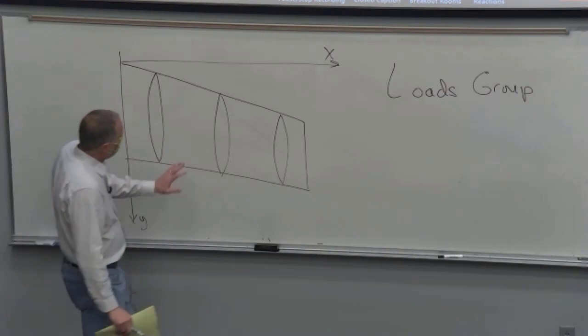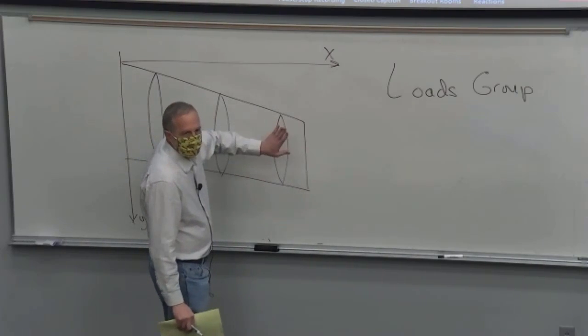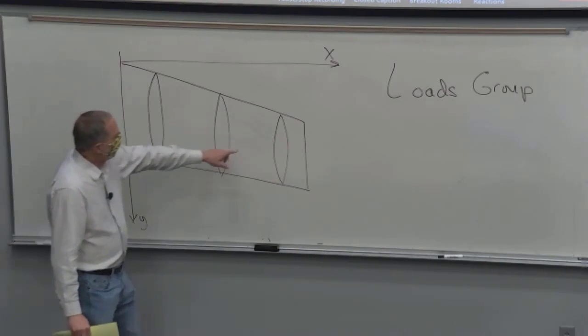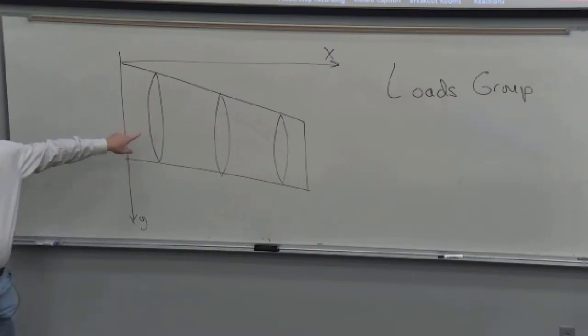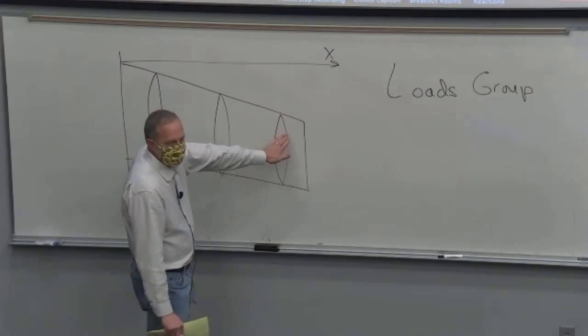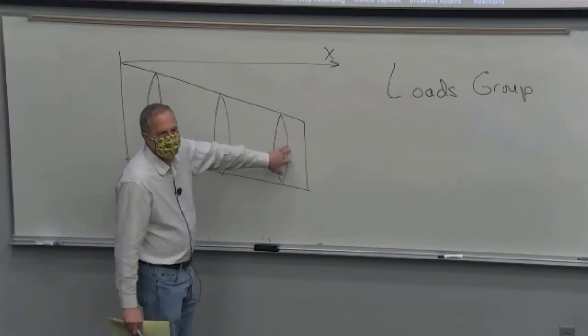But also, we could take the airfoil at the tip and twist it down or up. And a lot of times that's done so that the tip does not stall before the root of the wing. If you get the tip stalling, then you get huge rolling moments when stall happens, and that's bad. So typically you'll twist the tip a little bit downward so that this airfoil stalls before the tip.